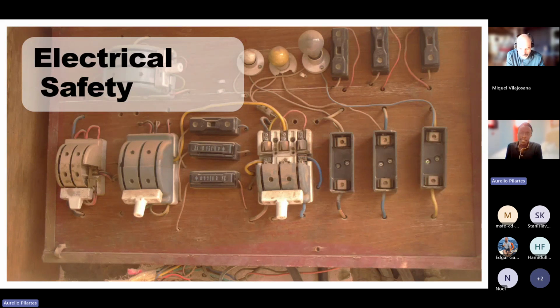Now, for most of the devices, and for all the devices that use a compressor, I'm talking about fridges, freezers, air conditioners, as you say, and this kind of thing, it's better to use an AVR. The AVR would be a very good option, because if you put a UPS there, this material with compressors uses a lot of power. So if you intend to put UPSs there, bear in mind you will have to buy big UPSs with a big bunch of batteries that most likely you don't want. So you put an AVR.